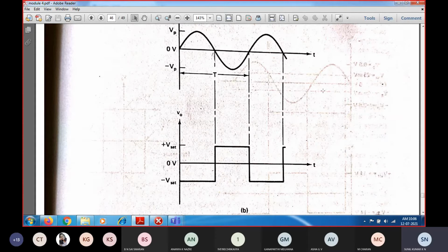These are the three different configurations, along with the differential amplifier configuration. In each configuration we have seen applications like summing, scaling as well as averaging amplifier, for the inverting amplifier, non-inverting amplifier as well as voltage follower. These are the fundamental applications of the negative feedback configuration. Then we started with the open loop configuration of the op amp.